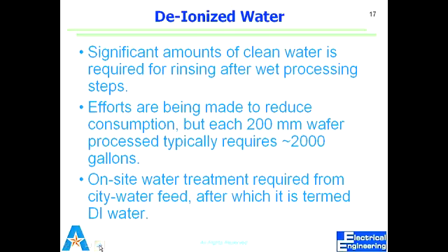Organics are very important, because what is an organic material? That contains carbon, and we say carbon everywhere. Carbon can make a film which becomes hard to remove. So we want to get rid of organic materials. We do on-site DI treatment. So these DI water systems can be as small as a bench top to something that fills up a room.